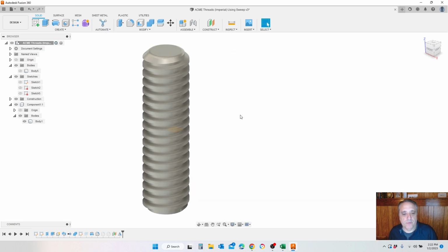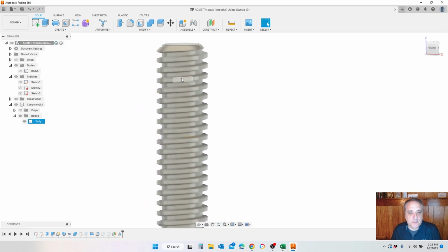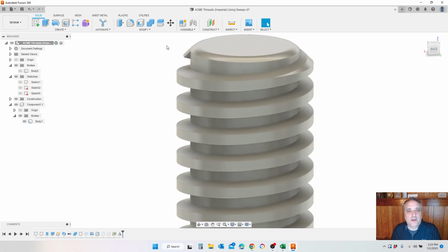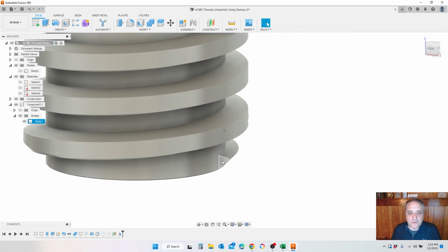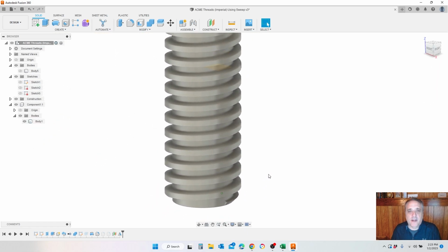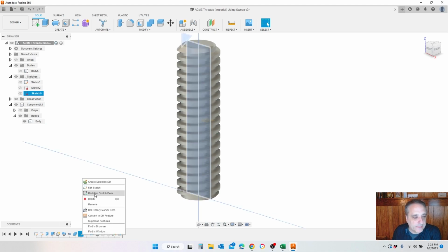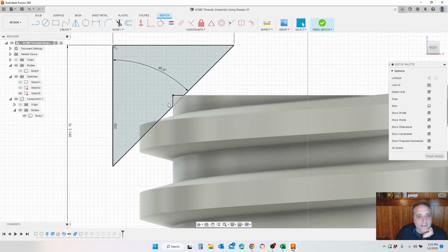Click OK on that. And now we're going to see some things can happen here when we do this, because it's never exact. So it did the calculation. I have a nice looking thing. Other than, if you look, we didn't quite cut that edge. See, we have those two edges that did not get cut out. So if that happens, we want a better lead in, then we can just go back and edit this sketch, and you can see why that is.